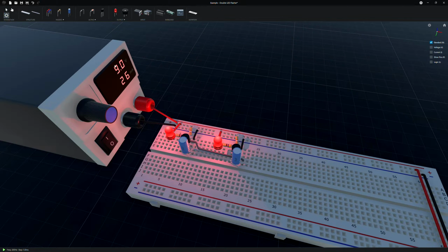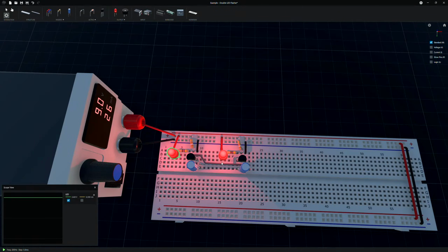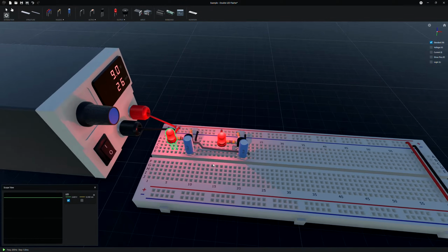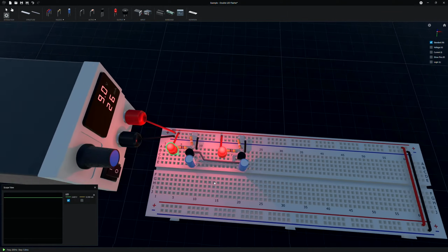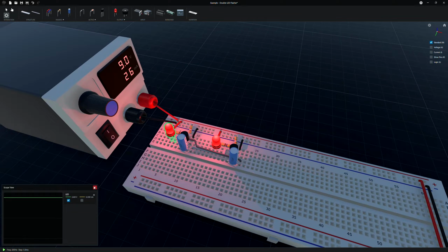And you can even throw the scope on the LED. You can see it's just a constant 2.42 volts. There's nothing going on here. And these are just two transistors basically tied together. So one should turn on and turn the other one off, and they should just oscillate back and forth based on this capacitor network. And I've tried building it several times. Just can't get it to work. So something is not right, or I'm doing something wrong.